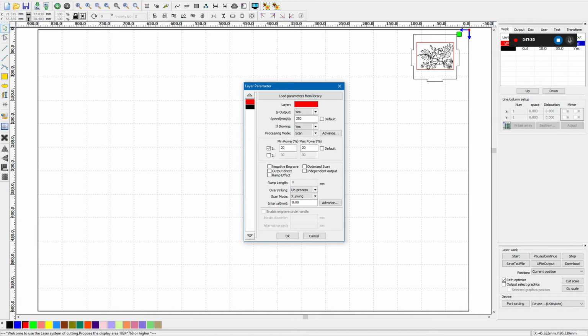However, Y swing can be used if, for example, the part has 2 columns of vertical lettering and the part can't be turned 90 degrees for cutting or engraving. In this case, Y swing will be much faster. We just avoid it if we can, as more mass has to move back and forth, creating more wear on the mechanics of the laser cutter.